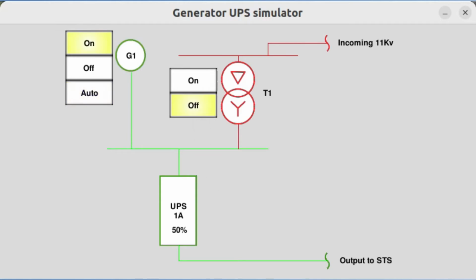You'll also see that the charge of the UPS depleted initially, and then it started to charge back up when the power is provided by the generator. This is all done automatically, ensuring that this is seamless to the end user. When the power is restored from the electrical grid, then the switch back to the main supply is normally done manually to ensure that the main supply is stable first. And then it's restored to auto mode, so that it will automatically start when required.